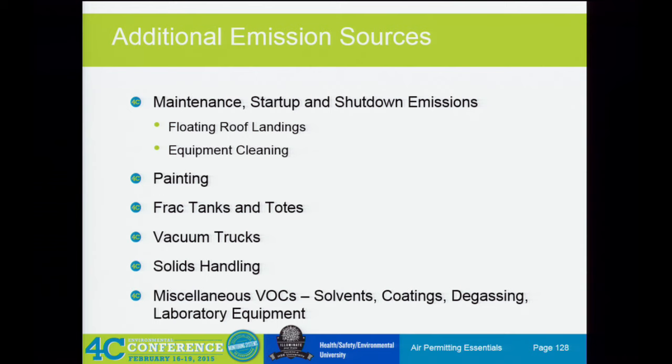Nope, didn't do a lot of dust stuff. Usually the reason we don't do a lot of dust stuff is because they are also another type of process vent. So you would calculate the emissions very similarly to what you would do with a process vent. Calculate a flow rate of your particulate matter through that vent and apply a control efficiency to the bag house that you would use to control those emissions.